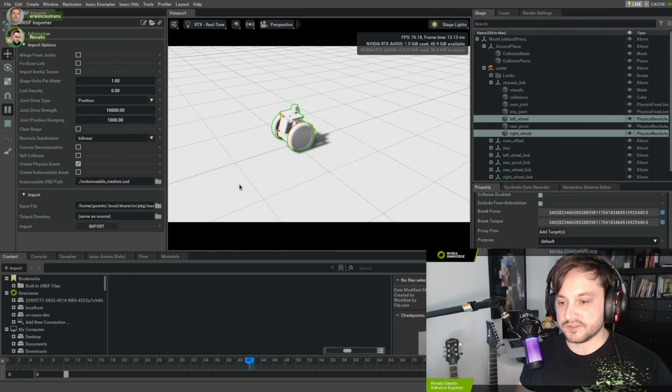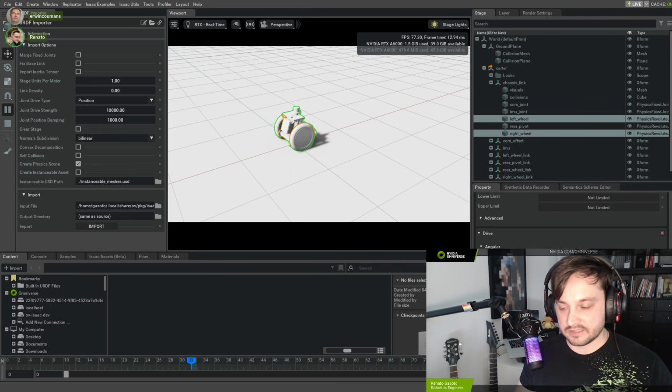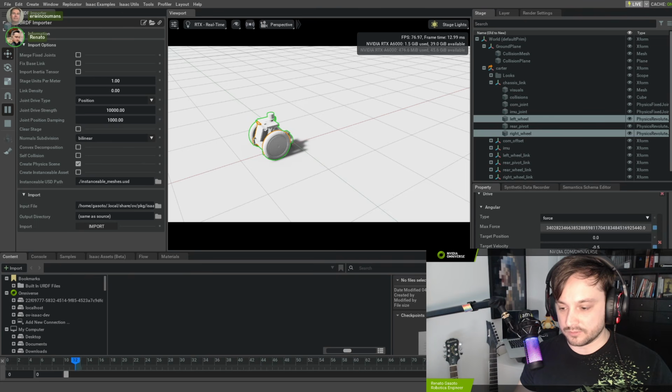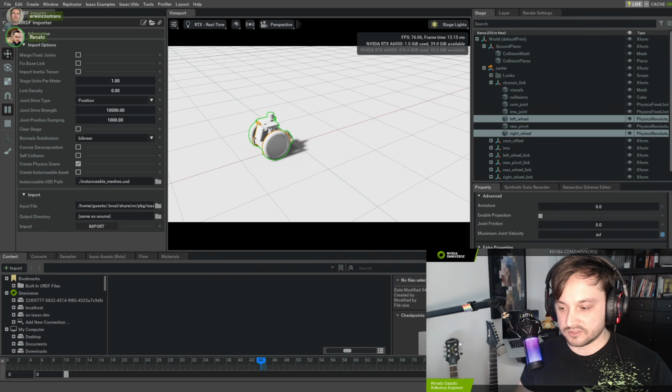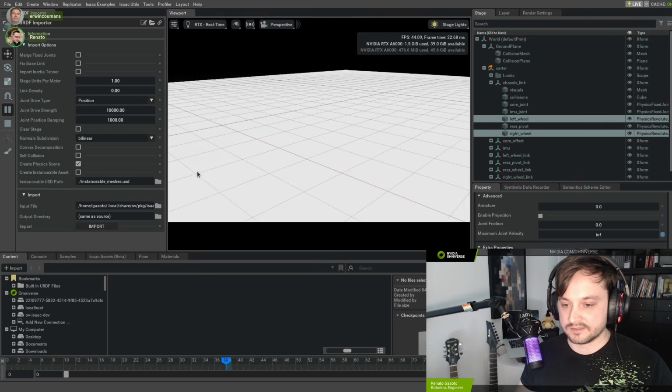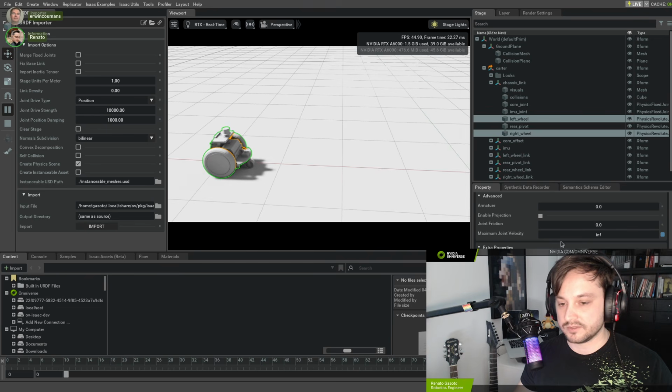And here's an interesting tip. If you select multiple joints, you're gonna see, oh, this one does let set the velocity here, but you see that it doesn't change until I release it, right? Even here, it does have a velocity there, but it doesn't change until I release it. But if you go here on raw USD properties, skip multi-selection, and then change the target velocity here, it actually applies it instantly. So this is a quick way for checking things if you want to see things moving on screen.